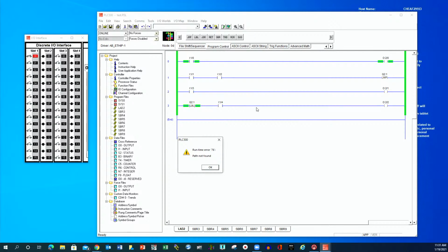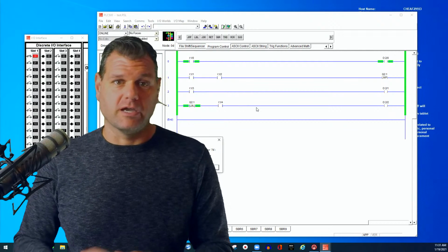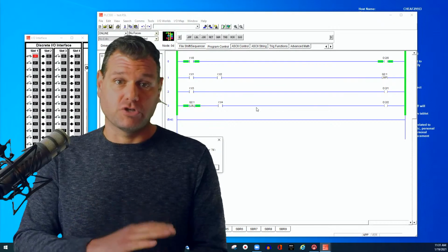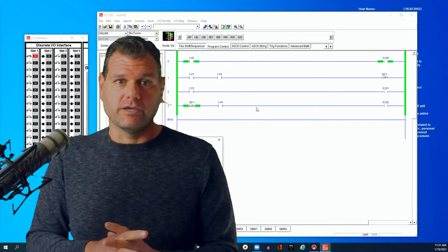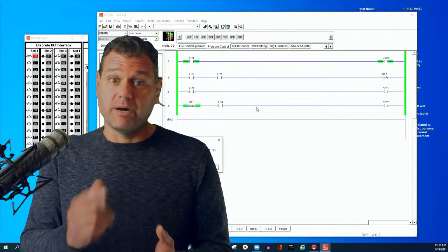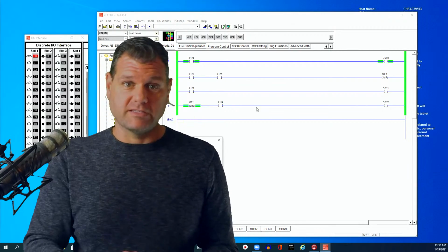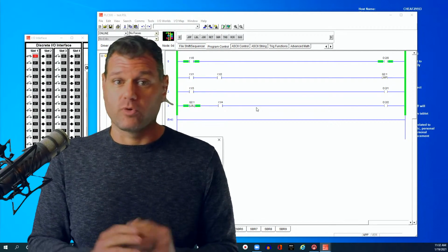You just have to be very careful not to put yourself in a loop, because if you're in a loop, it will slow down the scan process, and then something called a watchdog timer, which is like the master timer for the whole program, will eventually kick in and say something's wrong, I'm going to shut it off, and you have a fault. So if you have it constantly going in a loop, it's going to mess up. But you can jump backwards and scan something once again before the end of the scan.